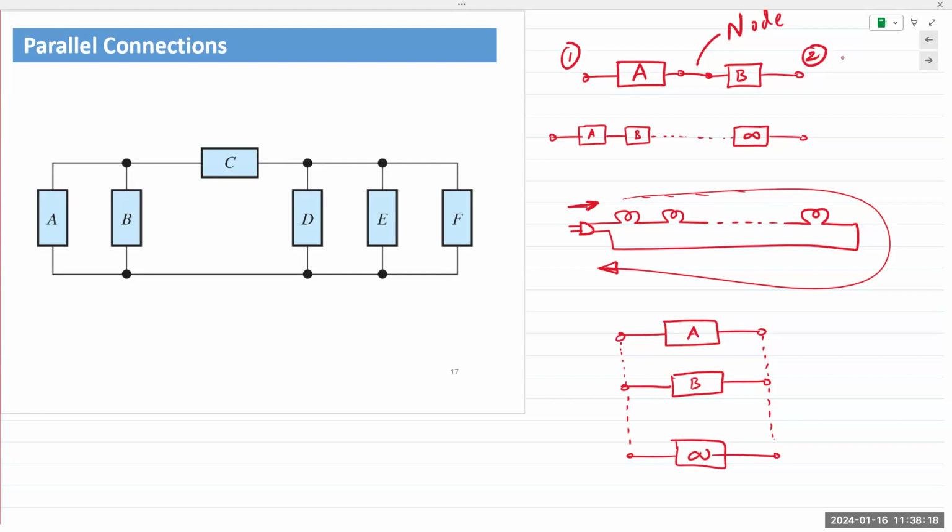Coming back to the example of the lights, modern lights, whether they're LED or light bulbs, have sections of lights that are in series, but those sections are then connected in parallel. That's why I said old lights, all of them are in series. Modern lights, you have multiple sections. Those sections are connected in parallel. So even if one light bulb in a section goes out, it only affects the light bulbs in that section.